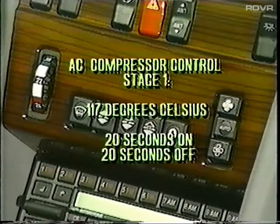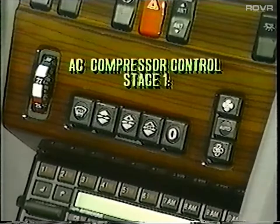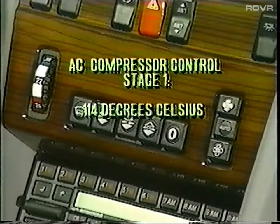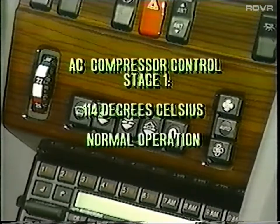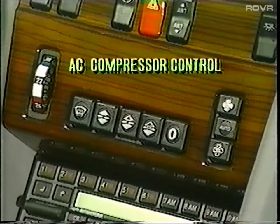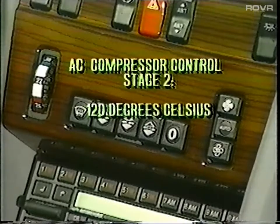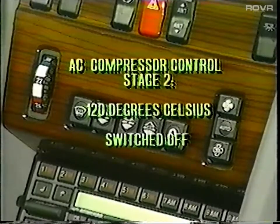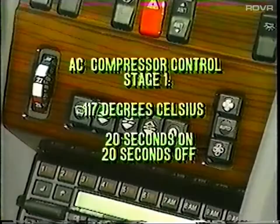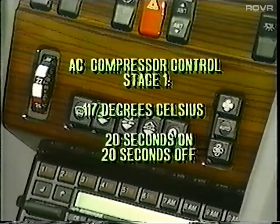Cycling 20 seconds on and 20 seconds off. If the coolant temperature drops to 114 degrees Celsius, the compressor will again resume operating in the normal mode. But if instead of falling, the coolant temperature should continue to rise, at 120 degrees Celsius, the compressor is completely switched off. When the coolant temperature drops to 117 degrees, the compressor will again cycle 20 seconds on, 20 seconds off.